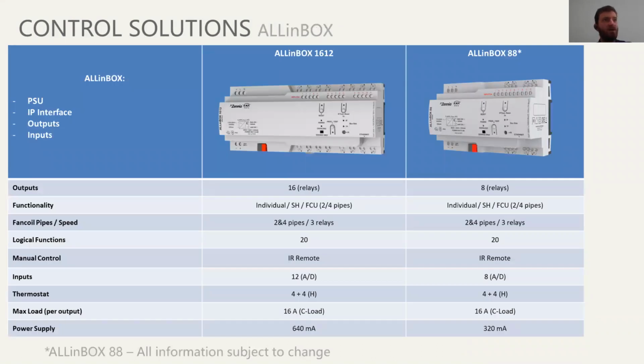So some of the fan coil controllers in the Zenio family. Again, fan coil control is just a matter of logic. If you are controlling a fan coil with relays, it's just a matter of defining how the relays are going to work together. So in Zenio, we build fan coil control logic in a lot of our devices. For example, the new family, the all-in box, which has just recently been made available for the general public, or for the integrator public.